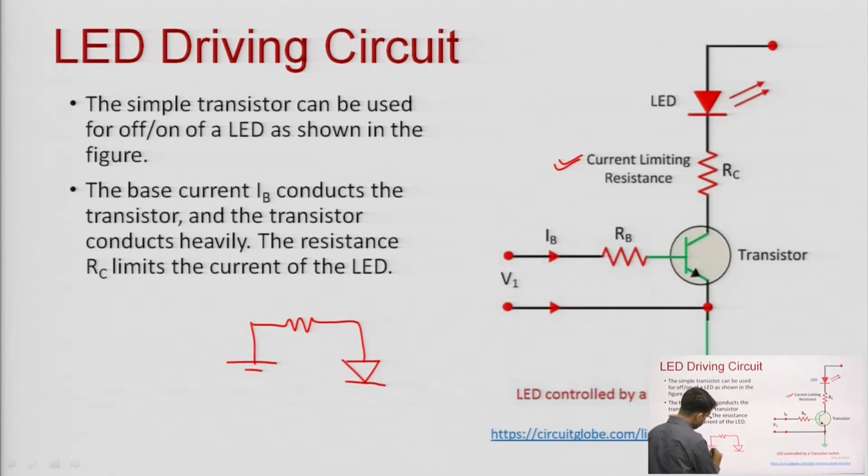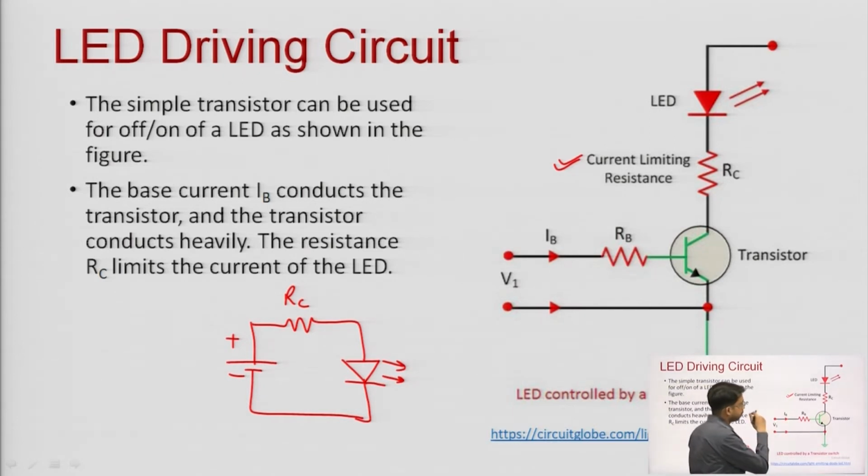and connect an LED with the battery. So, this will also work, the LED will be on, but we normally have to control the LED through some other signal, right. So, this is the current limiting resistance and this is the LED. This circuit will also work, but if we have to connect the LED with a microcontroller or a microprocessor, and if we wish to control the LED using some program, then we normally use this circuit.